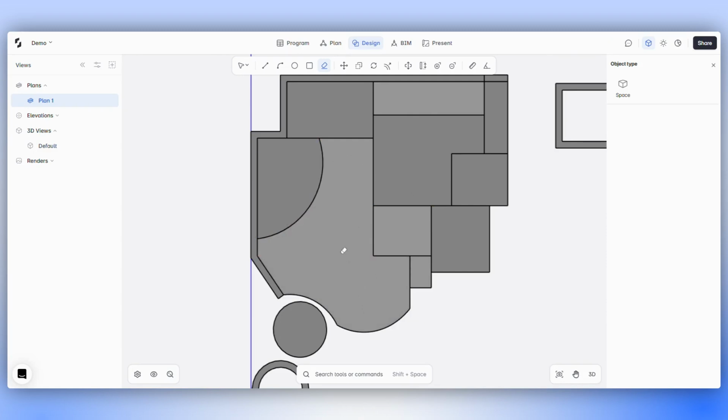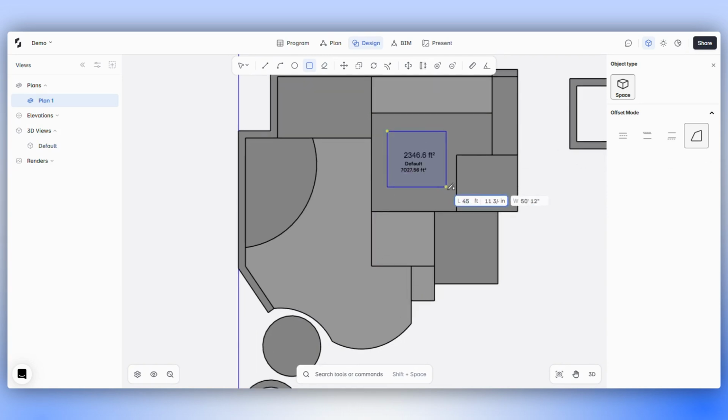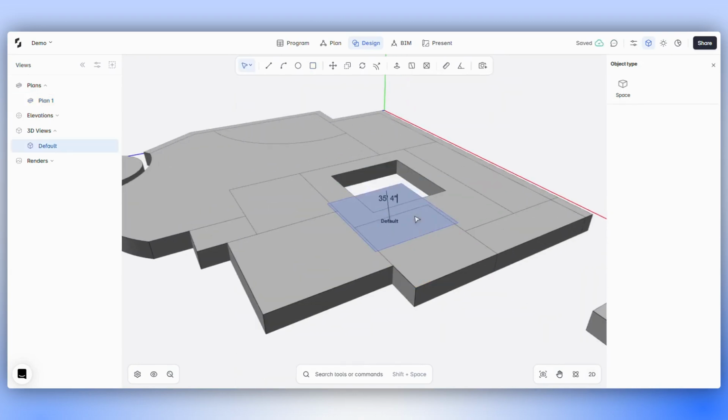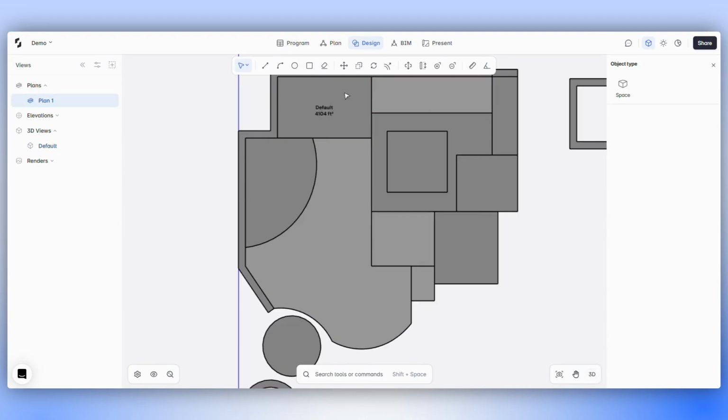Let's now delve into creating embedded spaces. Initiate this by clicking on the rectangle tool. Remember, embedded spaces can only be created using the rectangle or line tool in freeform draw mode. Start by sketching a rectangle within a space. You'll notice that it embeds itself within the space you've created. Follow a similar process with the line tool.